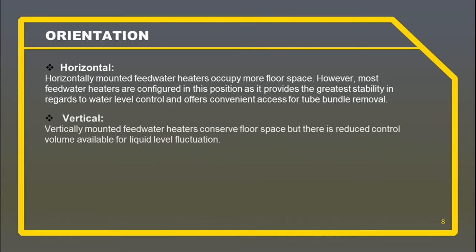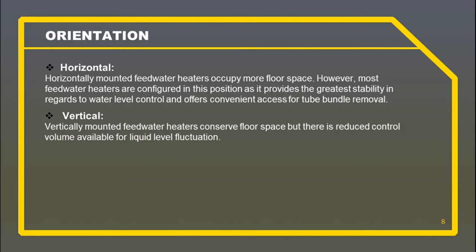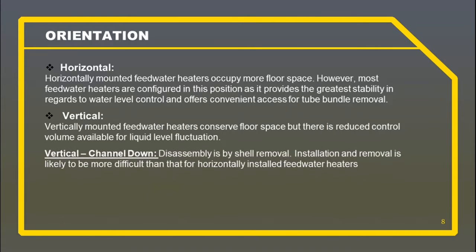Second is the vertical. Vertically mounted feedwater heaters conserve floor space, but there is reduced control volume available for liquid level fluctuation. Vertical channel down. This assembly is by shell removal. Installation and removal is likely to be more difficult than for horizontally installed feedwater heaters.